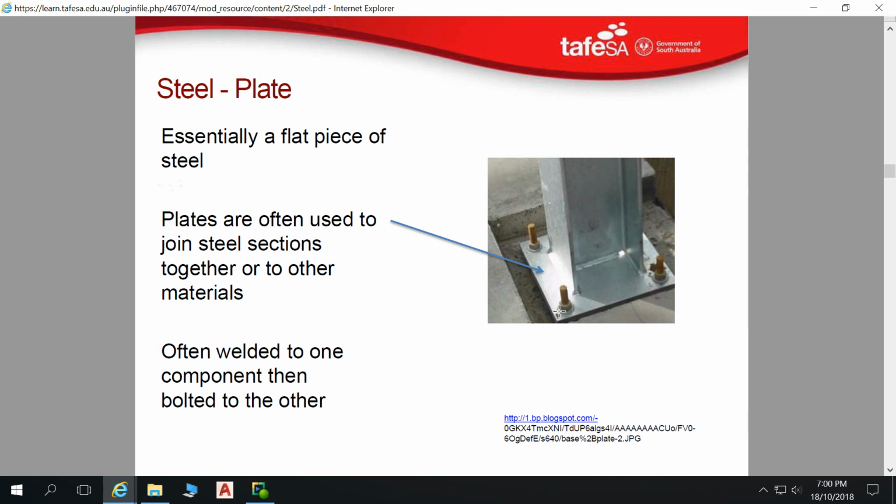So you can lift it up and pull it down to get everything exactly level and in place. Also, these holes in our flat plate might be slightly larger than the diameter of our threaded rod, to enable some minor sideways adjustment. But the best case scenario is that these threaded rods are placed very accurately during the concrete footing pour.